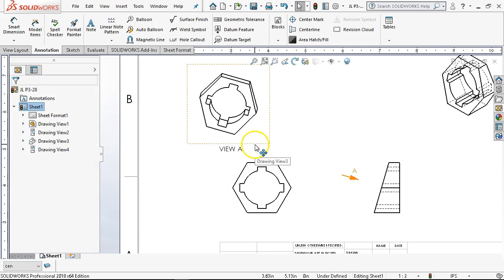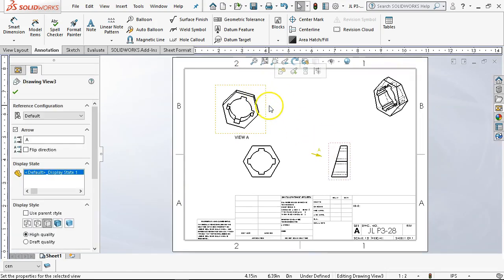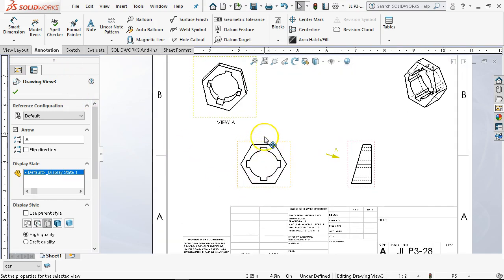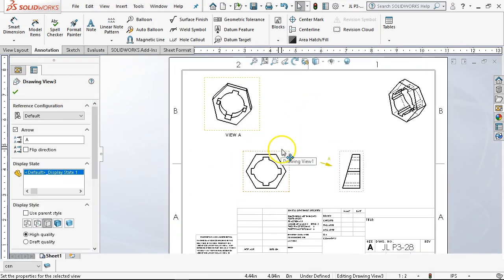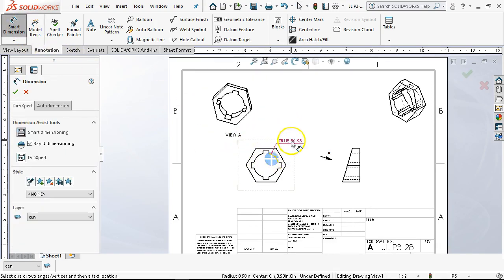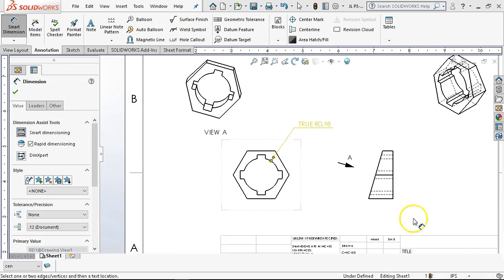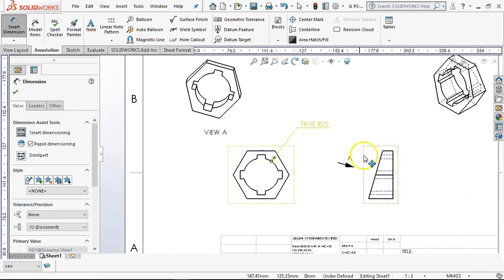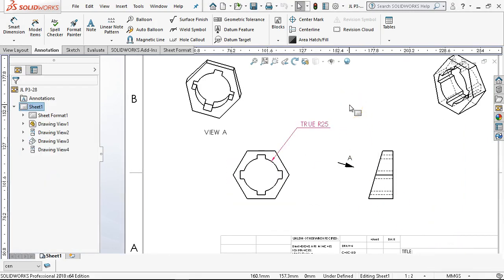All right, so with the weird angles, the selection there. Let's see, that one's going that way. It might be part of it's the rotation too. All right, so I'd have to work through that one to actually get to a dimension that we like. Would probably not. Well, let's see if it'll apply. True 0.98. All right, so we're back into that millimeters, grams, and seconds. And because it's off at an off angle, true position is in relation to that angle, as opposed to a normal plane.